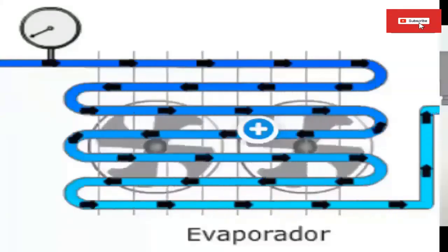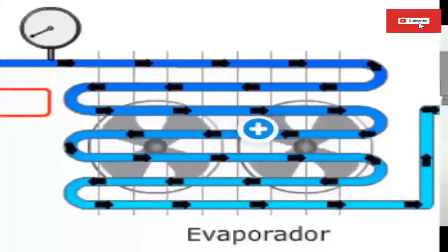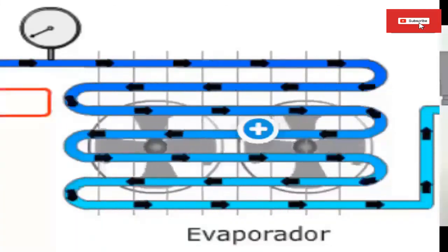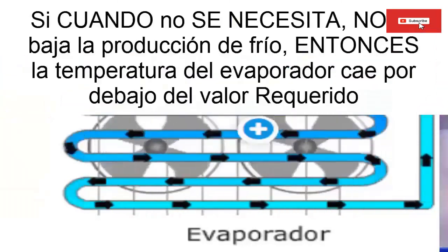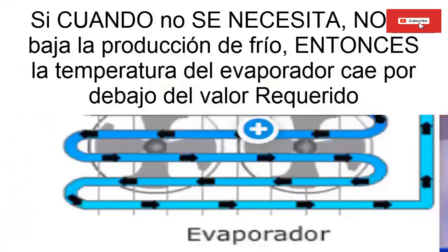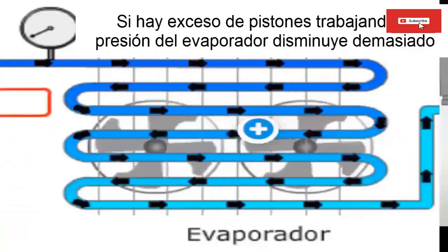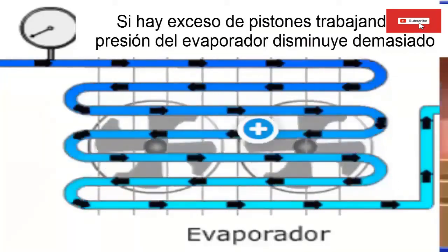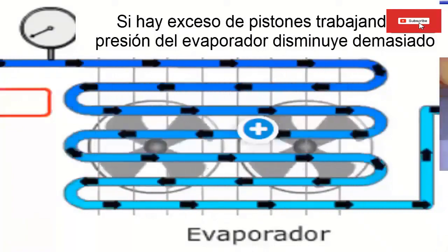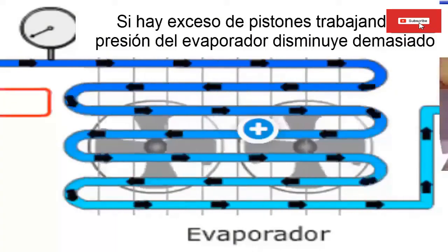2. By not taking a control action, the compressor is left operating at a lower evaporating temperature, which can affect the refrigerated space. 3. The evaporator temperature during part load conditions is reduced as the rate at which refrigerant vapor is drawn into the compressor exceeds the rate of vaporization in the evaporator. 4. Low temperature operation of the evaporator can cause problems such as low air humidity, frosting of the evaporator coils, and freezing of the external fluid.